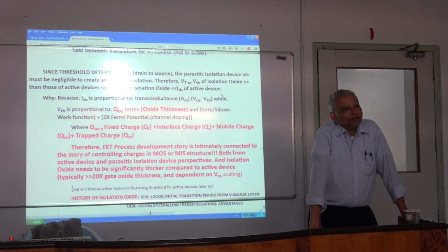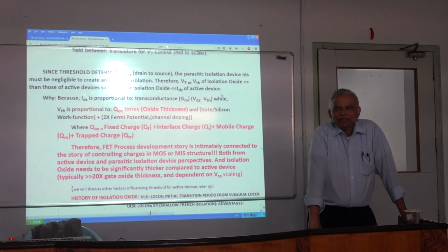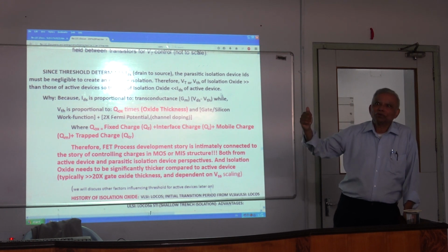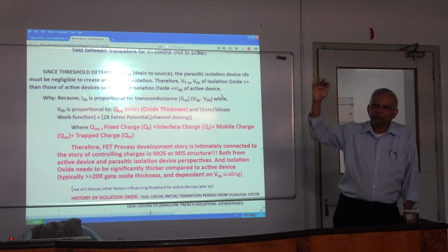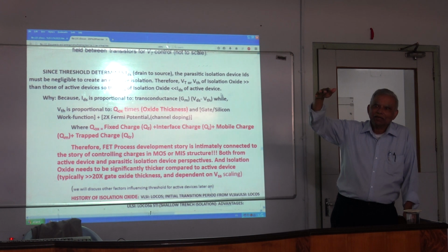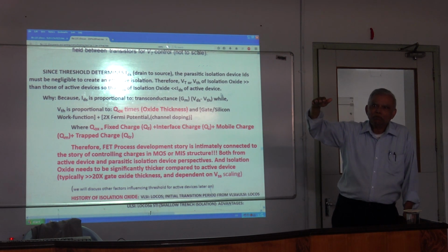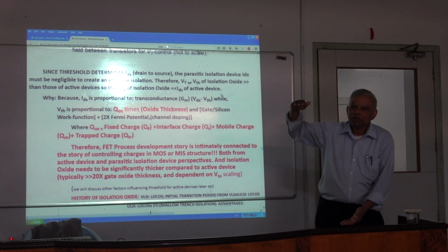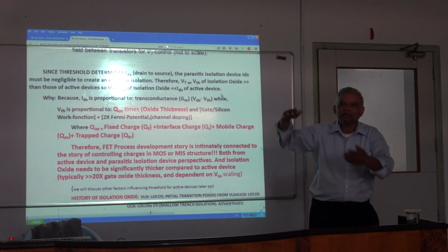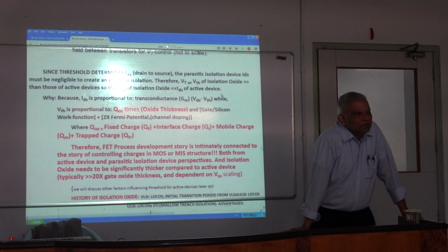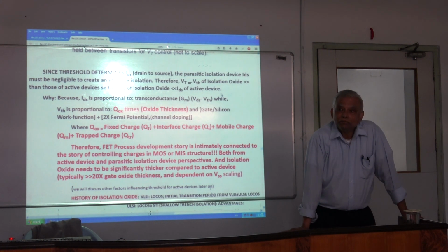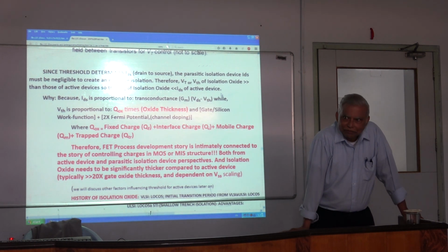But now you turn around and try to do NFET. That is going to raise the threshold. And not only that, it moves with the field you put in the gate, right? So it depends on what gate potential you put. So sodium can move all over the oxide, very readily mobile, even at room temperature. So your threshold shifts, and that's not a reliable device.